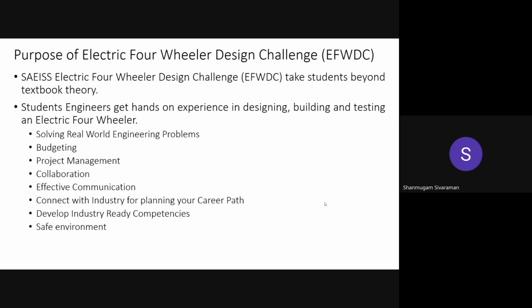That's the component level. At the assembly level, or at a system or product level, you can have failure modes like no function or partial function due to usage or time. The third one is intermittent function, and the fourth one is unintended function. So it could be any one of these reasons.